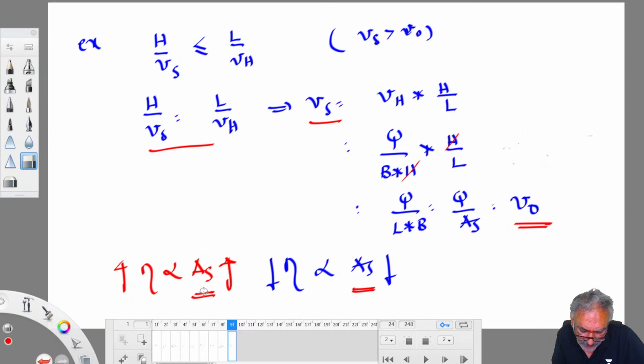Surface area influences particle removal. It is not the depth. That point you have to remember. Surface area increases, efficiency also increases. Surface area decreases, efficiency also decreases. If this idea is there with you, any problem from any book you can comfortably work out. It is a cakewalk for you.